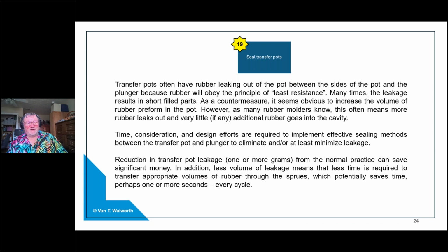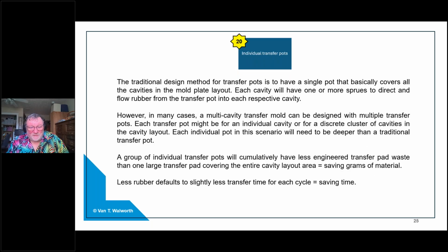Another thing about transfer pots. I definitely was, 40 years ago when I got into the rubber mold and rubber mold design and things like that, taught by some very wise people, and they pretty much said that, man, you got to have a pot that completely covers over all of your cavities. You really don't want your cavities to be sticking out from underneath the shadow of the transfer pot. I've long since found out that while that is good advice, it's not the only advice.